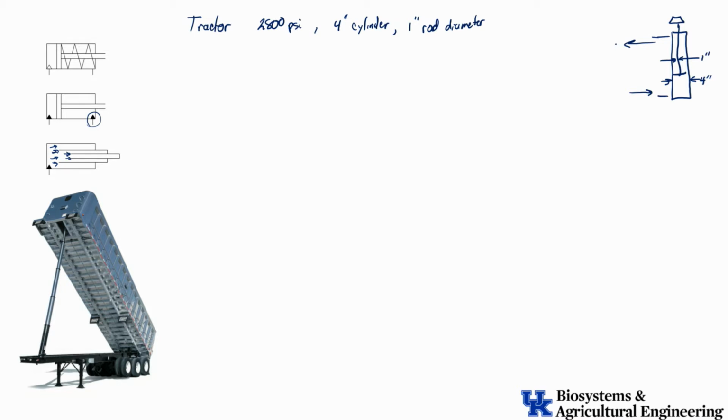But when it goes back into the tractor, and we'll see this in the lab when we test a tractor, you may have already seen it, there's probably a filter, some valves, whatever in the tractor to get through before this fluid can get back into the reservoir. So there's going to be some resistance to this flow. We talk about this as being the back pressure.